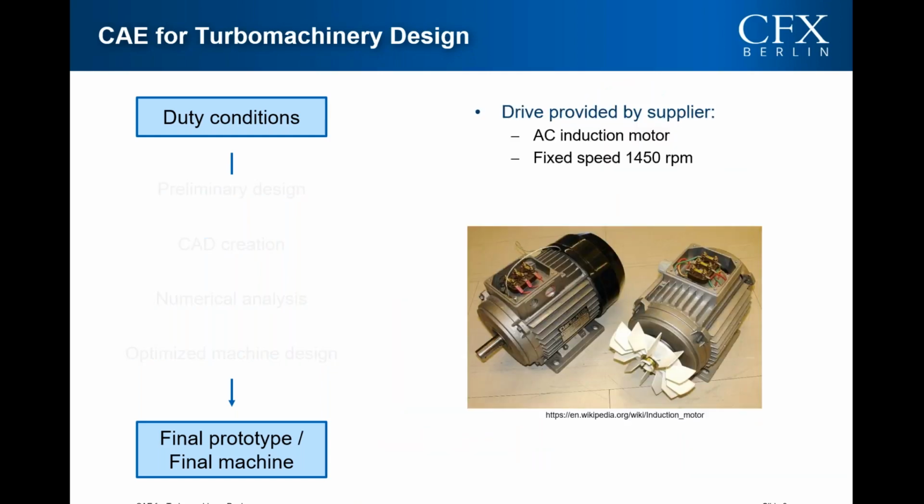In the present case, the drive is provided by a supplier. It is an alternating current induction motor, which is a common choice for pumping applications. It also means that our pump will operate at fixed speed conditions. So this is our first important design parameter.